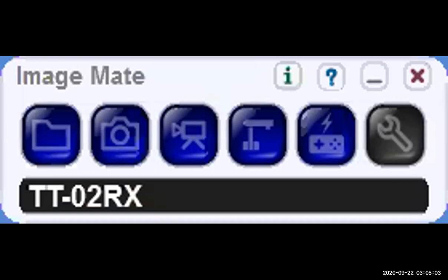for drawing things. Number 1, I selected the plane that I was going to work on, front, top, or right side view. I created a sketch. Step number 3 was to dimension the sketch. Step number 4 was to exit the sketch with a green check mark. Step 5 was to choose the feature, and I chose extrude. Step number 6 was to finish this feature with a check mark. You're going to need to know those 6 steps. In fact, we're going to have a quiz on those. There is a quiz coming. So you're going to need to write these down so that you can do well on that quiz.